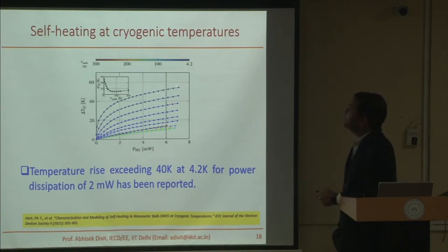That's why your junction temperature rise is more at low temperature. So it's equivalent to saying that the thermal resistance of my device has increased, which is 1 over the thermal conductivity. So thermal resistance increases, and the prevalent view is that the absence of phonon scattering is what is causing this.